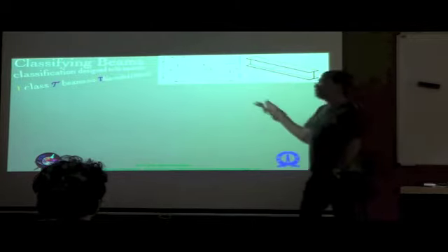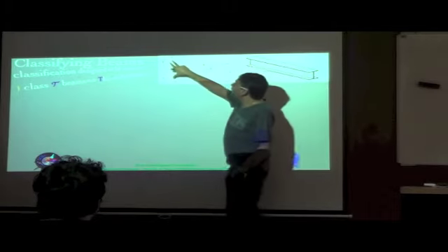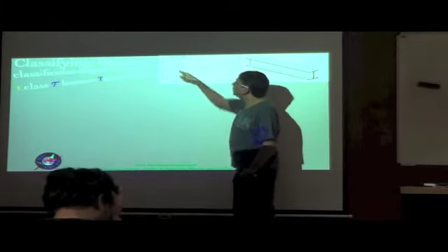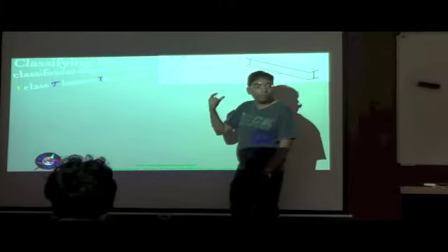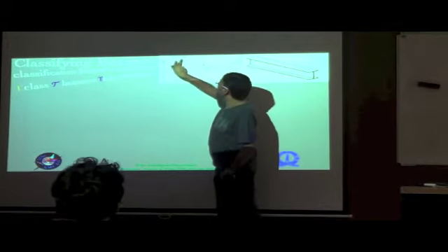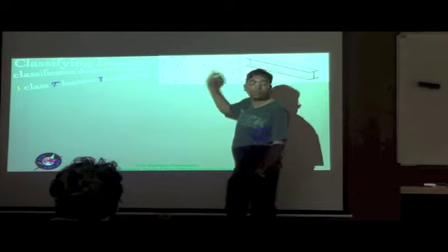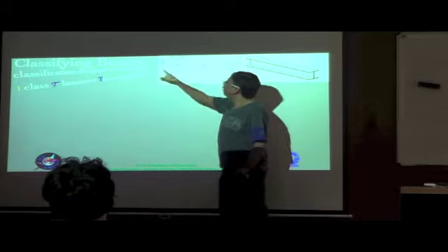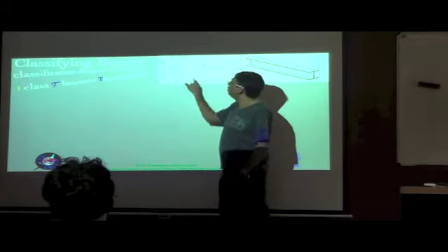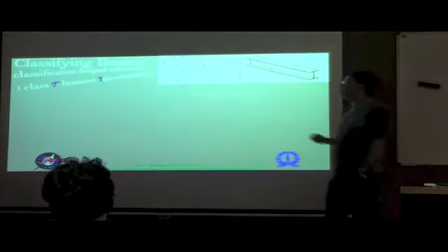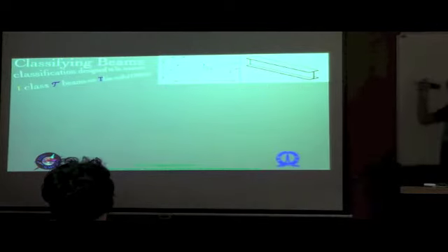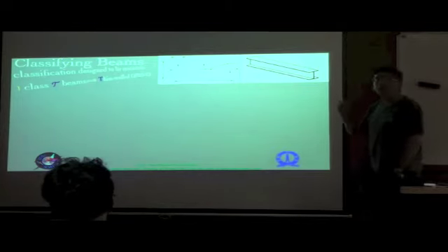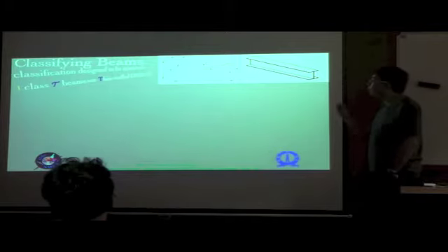An example of that is an I cross section beam, where the flange width and the web height, B and A, are of the same order of magnitude, but the thicknesses, let us say, of the flange and the web, which of course can all be different from each other, are of an order of magnitude smaller compared to B and A. In other words, H is very small compared to B and A. So these are the thin-walled open cross sections. Again, the I section is illustrative, but there are many other such beams like channel, hat section, Z section, cruciform, etc.